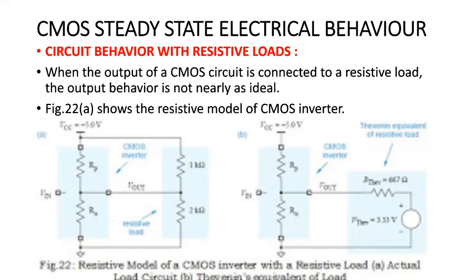If you observe carefully, NMOS devices offer lower resistance than PMOS devices, because the majority carriers in NMOS transistors are electrons, and electrons have a higher mobility compared with hole mobility. That's why NMOS devices naturally offer lower resistance than PMOS devices, so I am taking the NMOS low resistance as 100 ohms and the PMOS low resistance as 200 ohms.